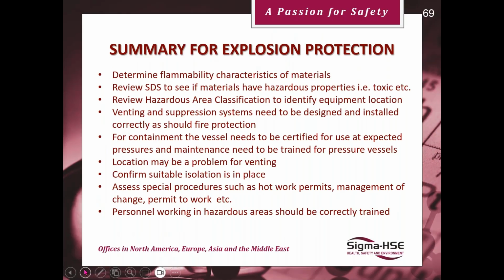Location may be a problem for venting as it has to go on an outside wall. Confirm suitable isolations in place. And assess special procedures, hot work permits, management of change, permit to works, etc. And management of change will give you an indication whether things have changed within your process and your selected basis of safety will operate still. Personnel working in hazardous areas should be correctly trained and the training repeated.